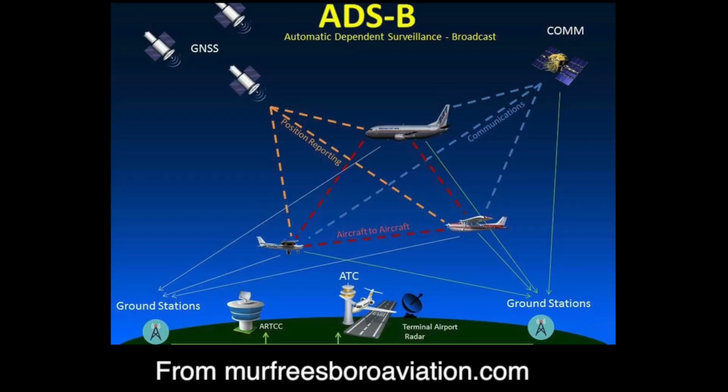First, let's start with what ADSB is. ADSB stands for Automatic Dependent Surveillance Broadcast. It is a signal that is sent out by an aircraft once per second, which includes GPS location, the altitude of the aircraft, their ground speed, along with a ton of other data to other aircraft around them that are equipped with the right equipment, as well as ground stations across the US. This data can then be used by air traffic control to more efficiently and safely control planes in the sky.